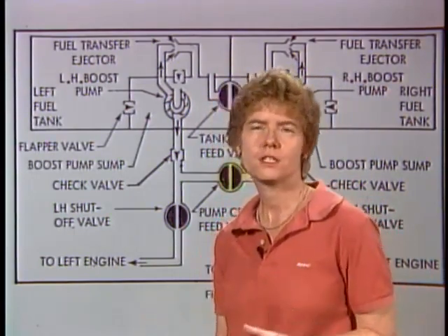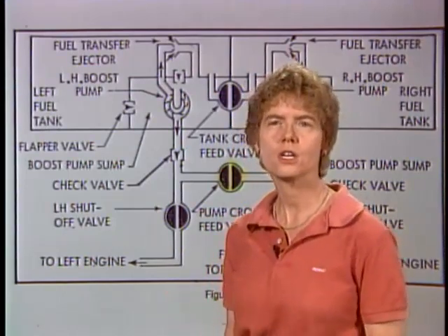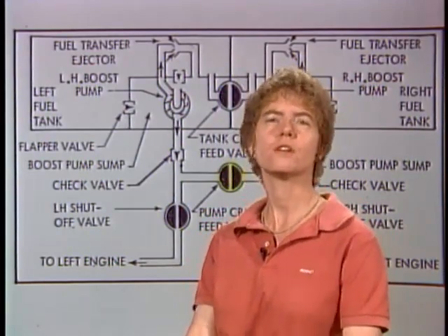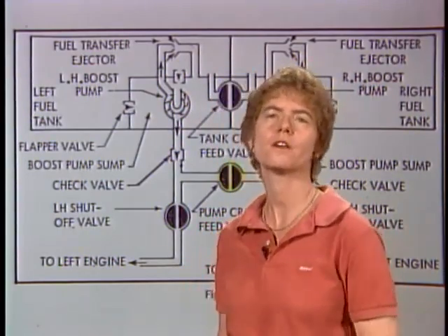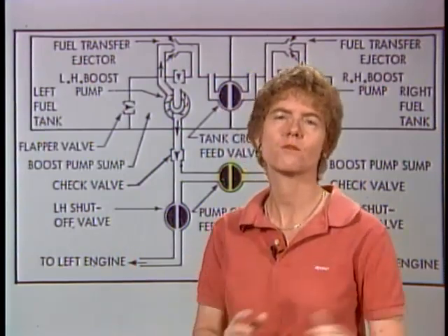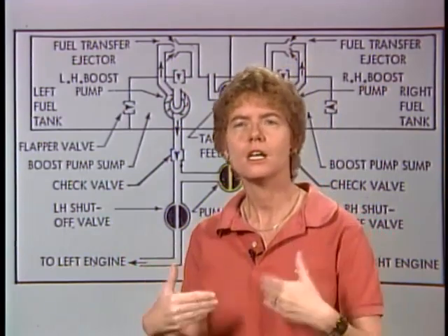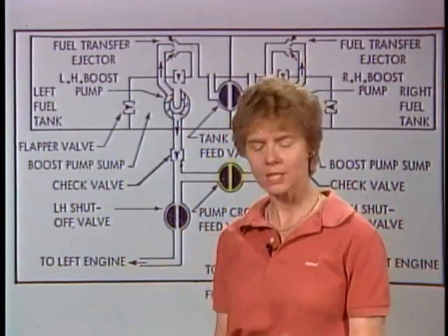Now, the cross-feed systems are used in multi-engine aircraft primarily to maintain a balanced fuel condition. If you've got more fuel in one tank than another, you can feed both of the engines out of one tank, balance the load, and then go back to feeding each engine off of its normal tank.